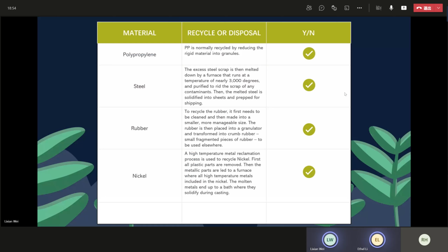Okay, my turn. About the environmental aspects, the first thing I will introduce is the box, divider, and lid. The material is polypropylene. Recycling of polypropylene has emerged as important and economically valuable on a large scale. The main benefit of recycling PP is the reduction in the consumption of fossil resources such as oil and natural gas. It is estimated that about 8% of the oil used worldwide is utilized in traditional methods of plastic production, with 4% as feedstock and another 4% in manufacturing. Relative to production from oil and gas, energy use can be reduced by 88% when plastic is produced from recycled plastic.